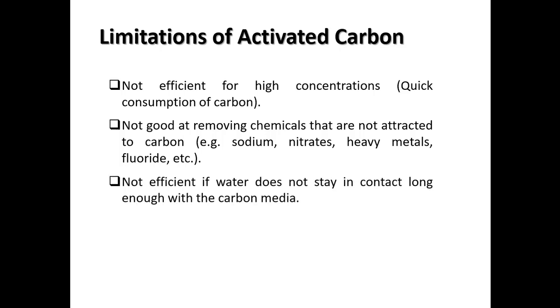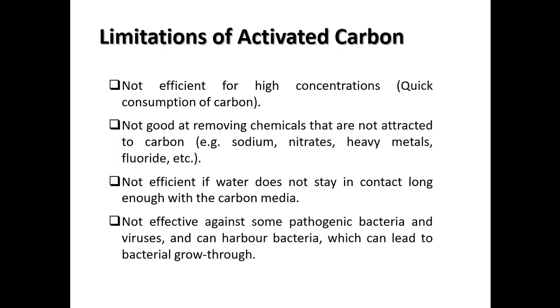Okay, and also activated carbon is not so efficient if the water does not stay in contact long enough with the carbon media. So we have to maintain a long contact time. We don't call it hydraulic retention time, we call it contact time. So if the contact time is not very long, the treatment won't be so efficient. So that's also a limitation. We have to provide longer contact time.